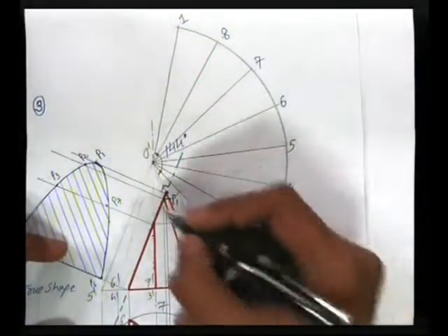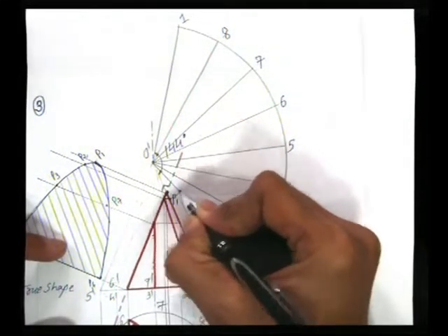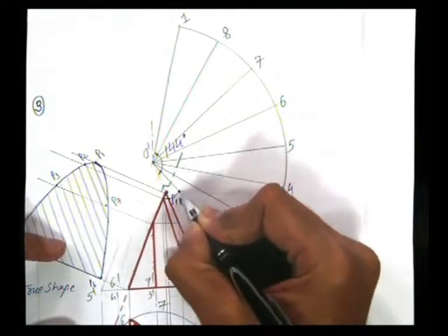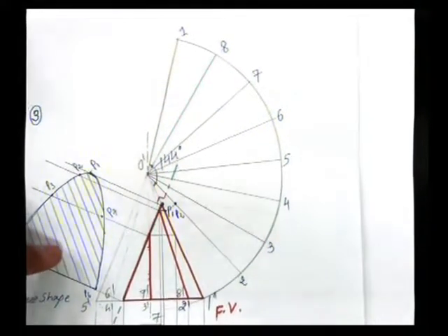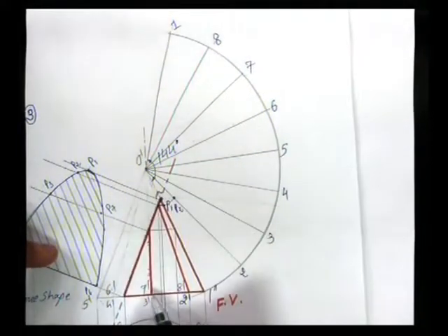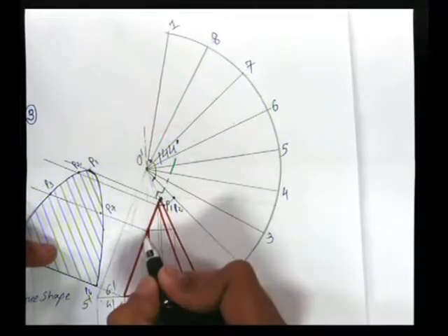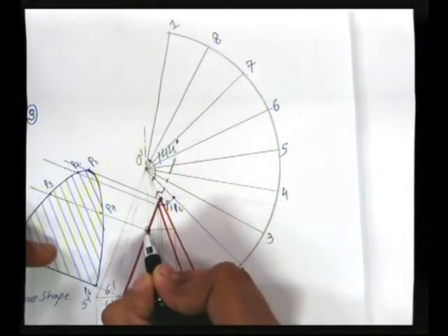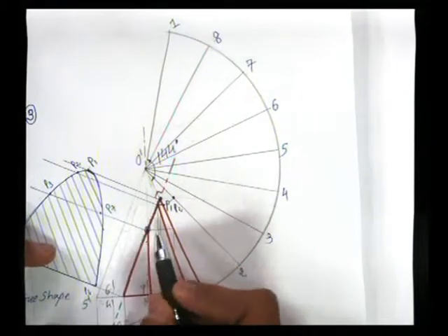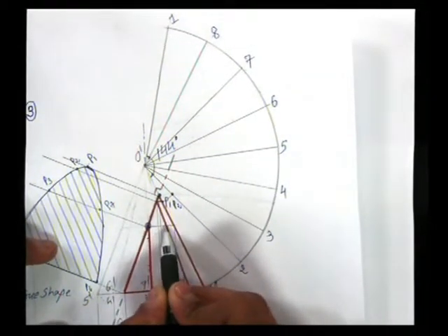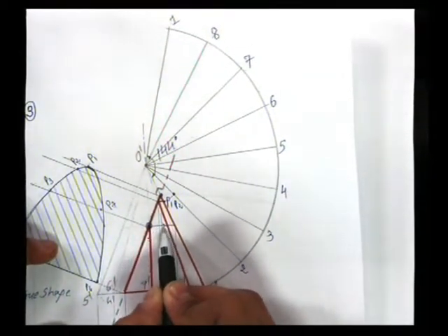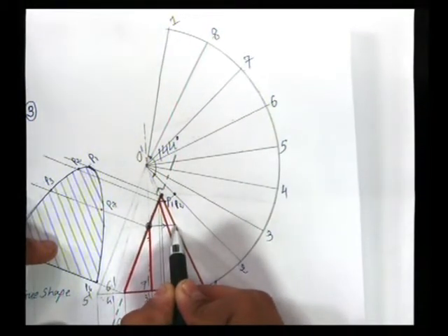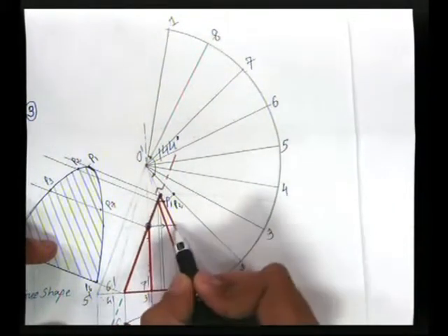This is O'2' at one point. So this is our point number P2, right? Now P3, here O3, O'3' is here. On O3 the cutting plane cuts at this point, so from this point draw a straight horizontal line like this, meaning transferring this point to its true length, so it will cut the true length O1 at this point.